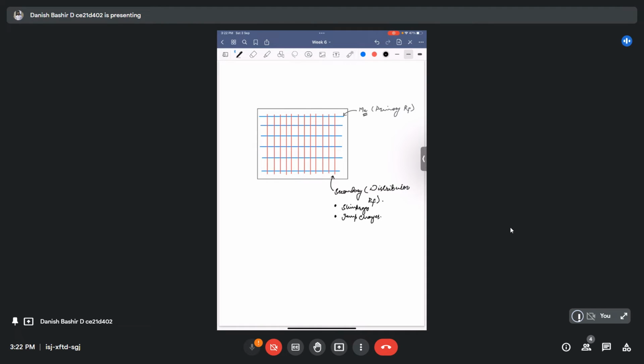this distribution reinforcement. Primary reinforcement is governed by Mu, the ultimate moment coming on your slab system, which will govern how much reinforcement you have to provide. And this distribution reinforcement is governed by the total gross area of your slab system. Since we are dealing with this slab as a beam of width 1 meter, the gross area will be depth times 1000 mm. It will be the gross area, A gross, for our slab.